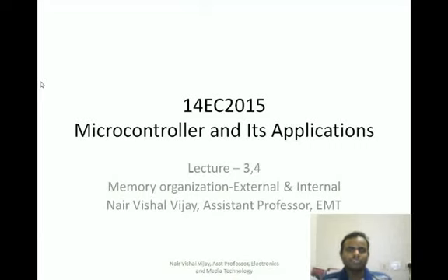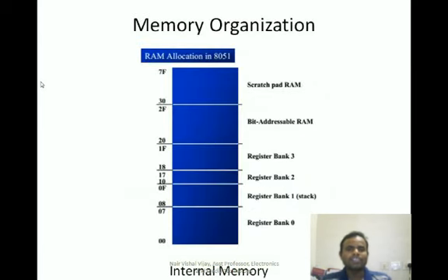Today we'll discuss the memory organization of 8051. We know that the 8051 microcontroller has an internal RAM and ROM. It has an internal RAM of 128 bytes and an internal ROM of 4 kilobytes. Now the capacity of internal RAM and ROM is very system specific.